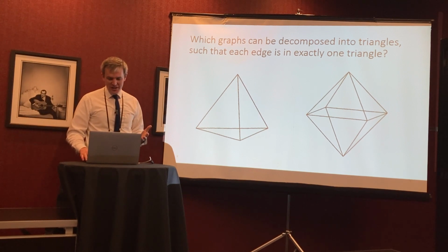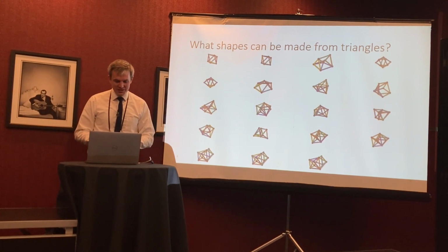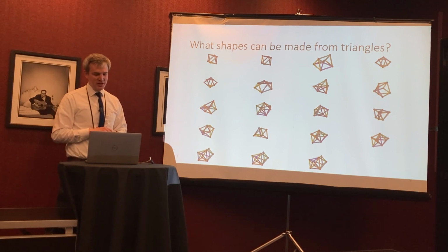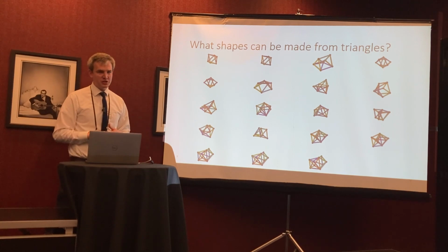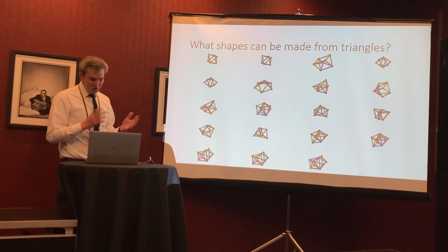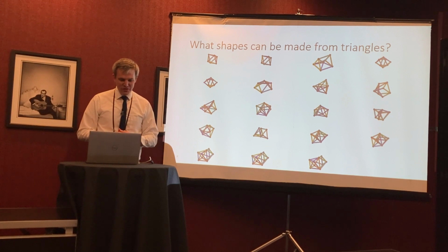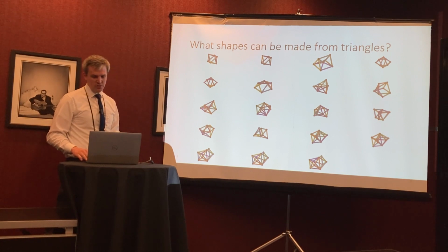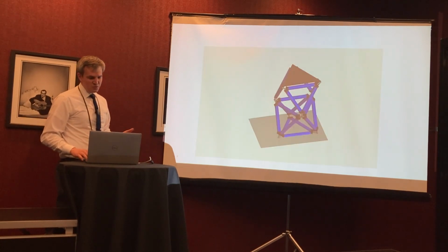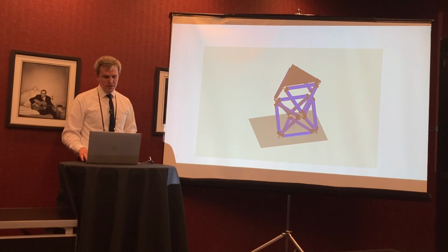And so what we've done is we've actually found a way to enumerate all graphs up to 9 nodes that can be decomposed into triangles where the graphs are minimally rigid or statically determinate. So we've borrowed some work from the graph theory community, and we've developed these 19 graphs here that we can decompose into triangles. And then using these graphs, we could stitch them together into larger shapes.